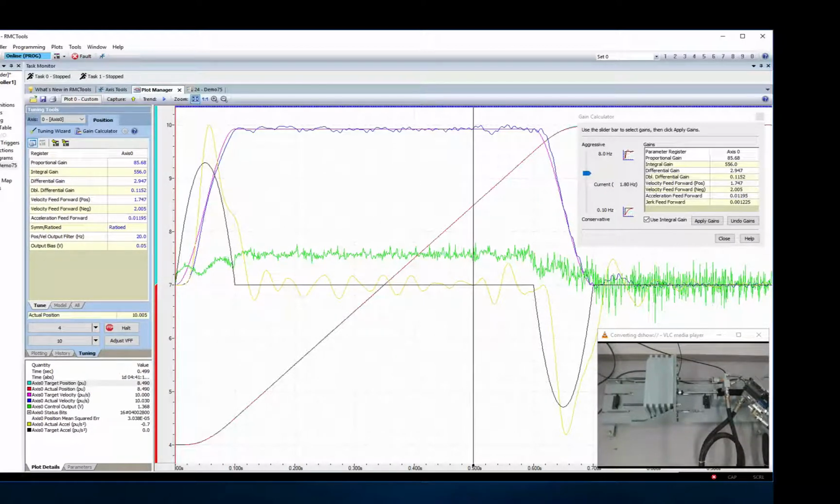So what does that mean cost-wise? Well, the diameter of the cylinder is roughly proportional to the natural frequency. So if you can reduce the natural frequency by about a factor of 2, you reduce the diameter of the cylinder by a factor of 2, but that reduces the area by a factor of 4. That means that you're reducing your pump size and your valve size by a factor of 4. And that's all money. That concludes the demonstration.